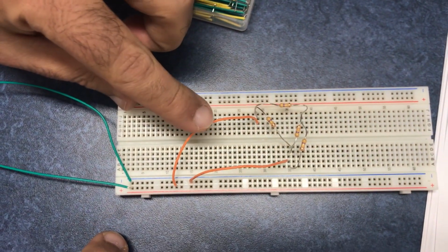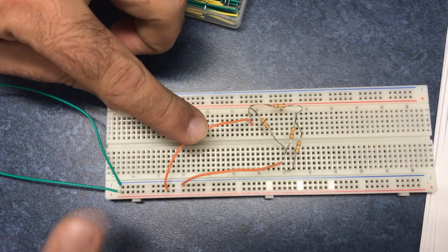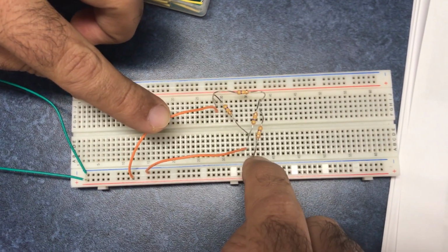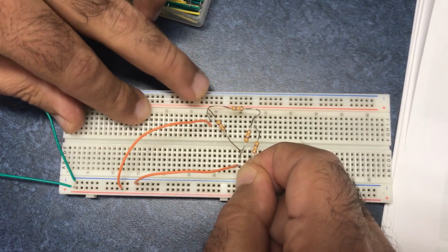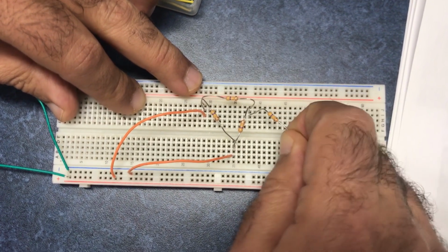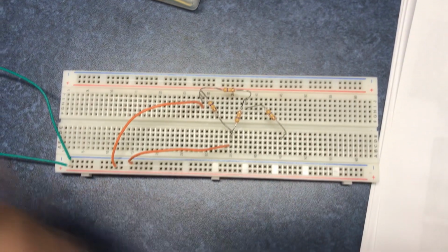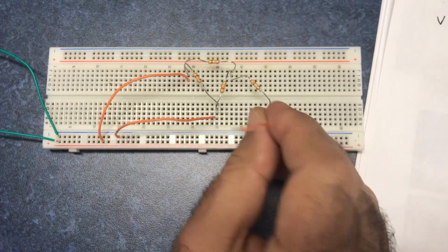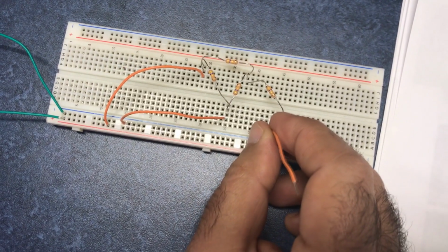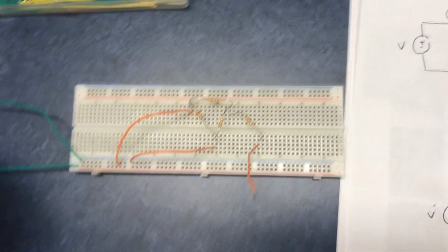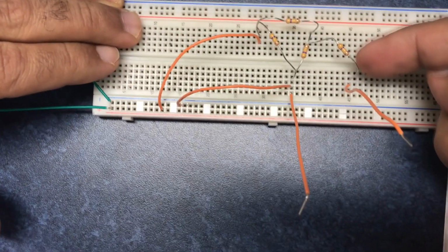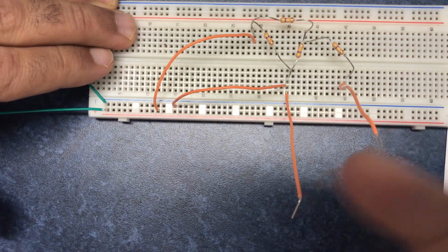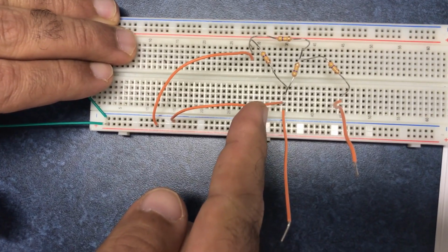What is needed? I would like to measure the current going to this. So I will connect here in series a meter. And I would like to measure the current in this. So what I have to do is I have to reconnect this. So for example, I'm going to put this anywhere. And then I will bring my ammeter and connect it between this point and this point. So right now the current is going from this to my ammeter. So I'll put my ammeter here and then going back to this point.